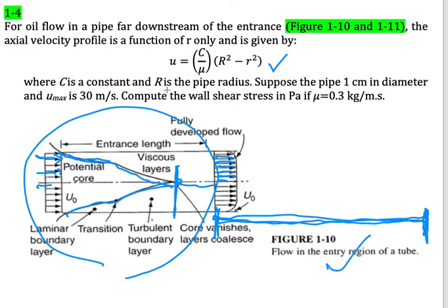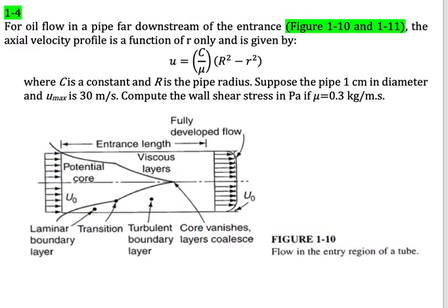Okay, and then the other thing is, I hope you could recall the idea of the velocity profile like this one. When water flows inside the pipe, there is an interaction between the solid surface and the molecules here, which creates the idea of the no slip condition. No slip condition means the molecules will not slip on the solid surface, so the molecules stick very hard on the solid surface.